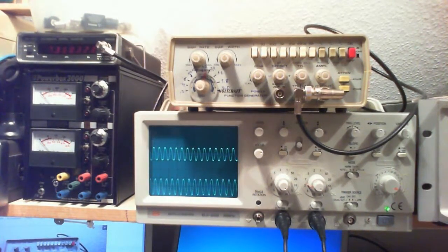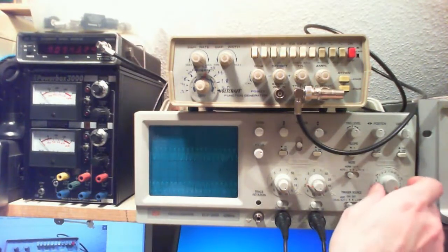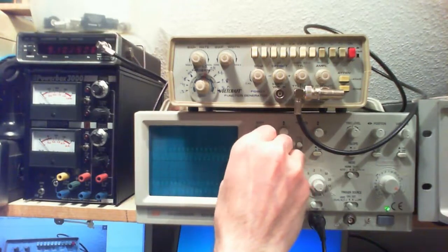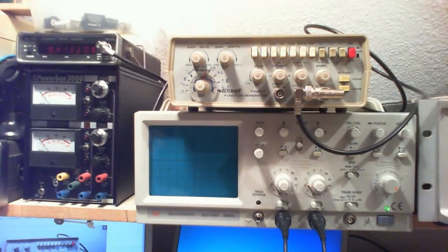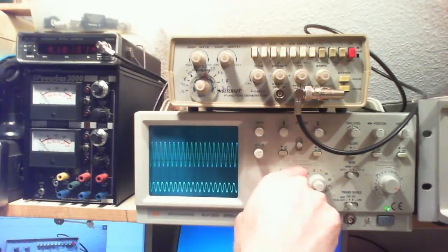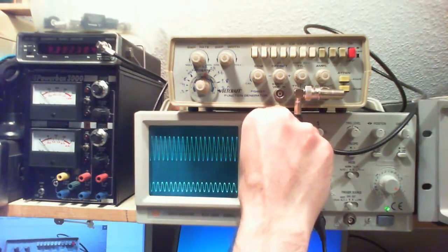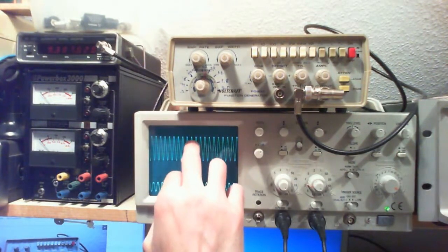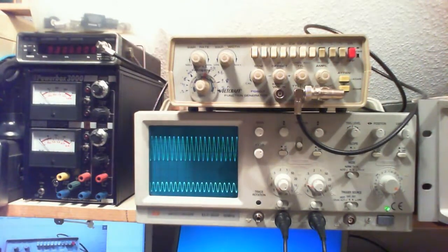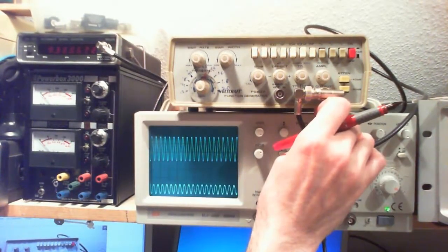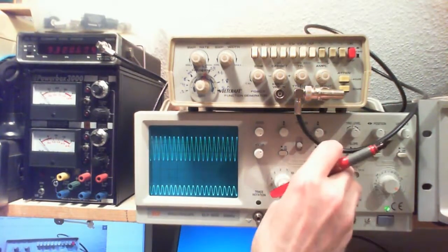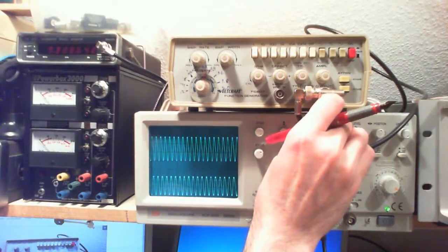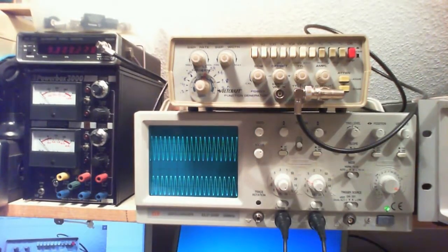And then at somewhere about, I don't know if you can still see anything, my input is right now at 2.8 times 5, which is about 14 volts, and my output is at, let's see what that is, 2.2 times 1, which is 2.2 volts peak to peak, and the frequency is 9.4 megahertz.